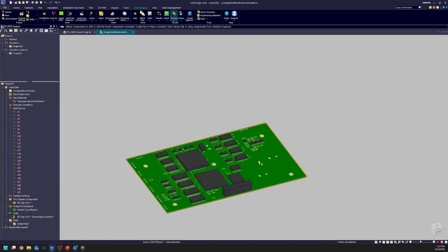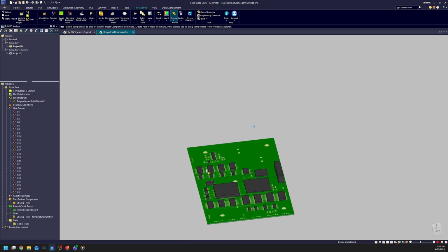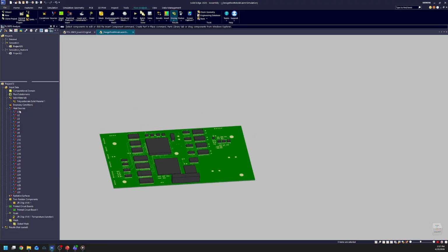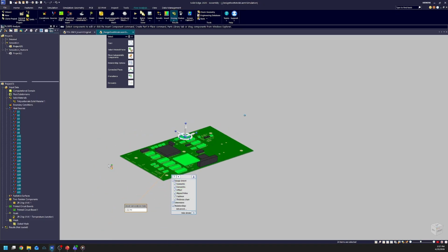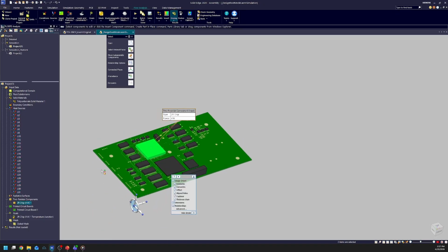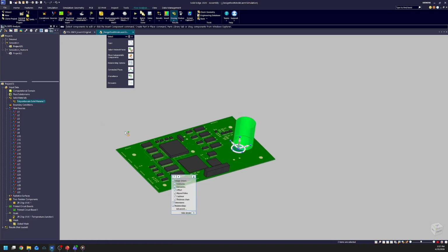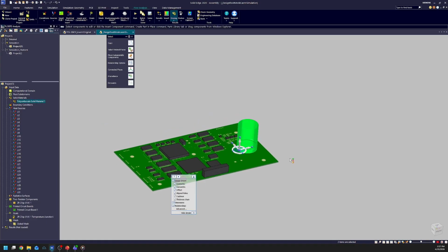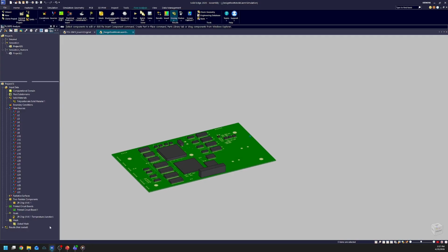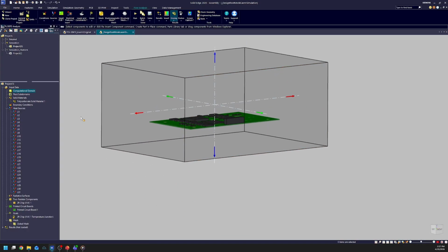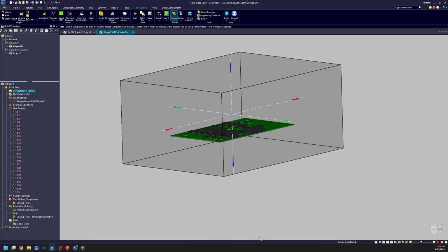I believe the two capacitors are still in the study. They're just not being shown at the moment. In this study, we have heat sources from all of these components, as well as the 2 resistor chip here, which is at 4 watts. The others are much smaller. We have some polycarbonate materials declared there. And this is the computational domain. So this is the volume that the solver is accounting for.